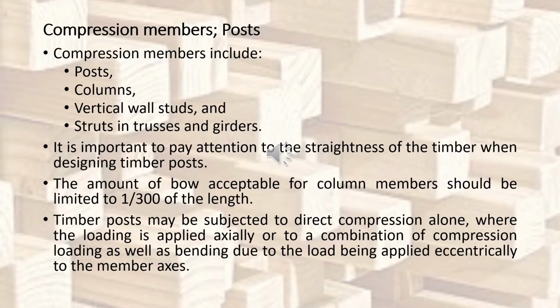Now, our interest here is with compression members. When we talk about timber compression members, we're basically referring to the design of timber posts. Compression members include posts, columns, vertical wall studs, and struts in girders or even in trusses. So it is important to carefully look at the straightness of the timber when designing those timber posts.